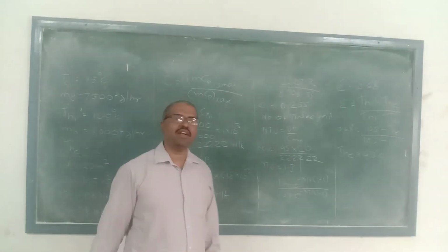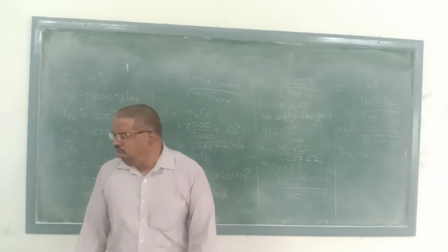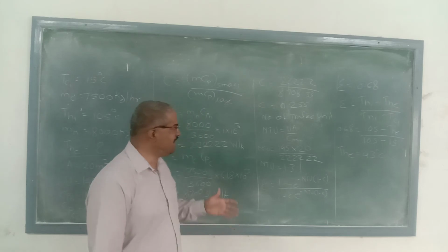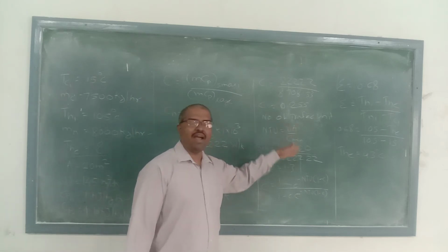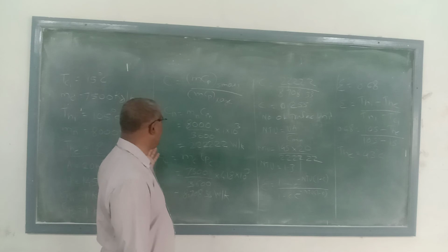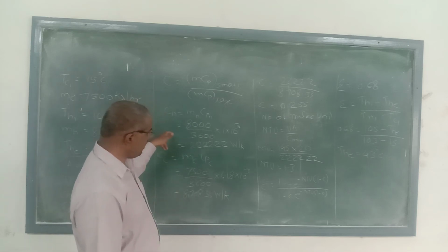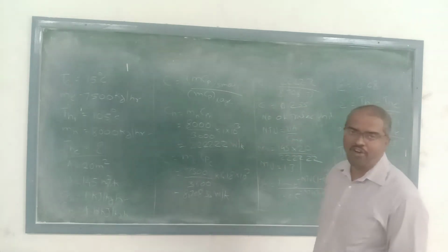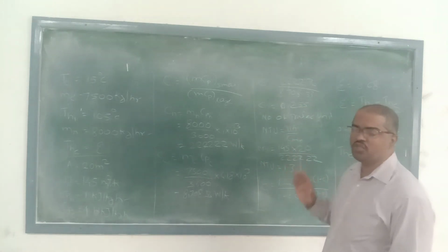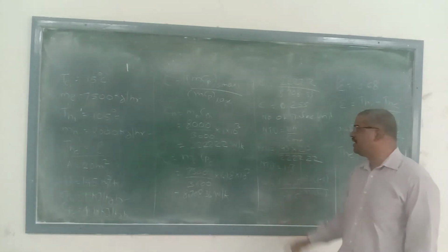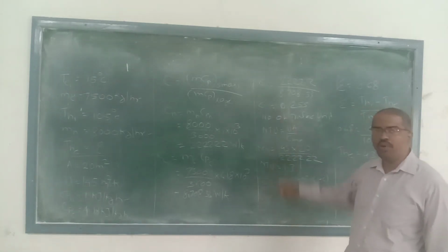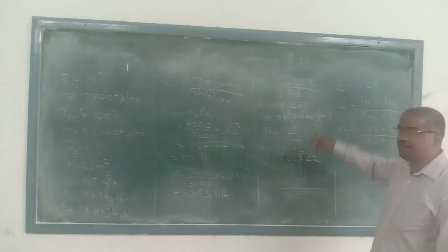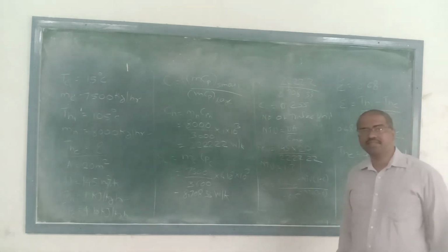Next, for calculating the NTU, it requires the overall heat transfer coefficient, the area, and C minimum. C minimum we have calculated, and that is CH. U, the overall heat transfer coefficient, they have mentioned. The cross section area is also given in the problem, so we can easily calculate the NTU. Once you know the NTU and C value, you can calculate the effectiveness. And here we are getting the effectiveness as 0.68.